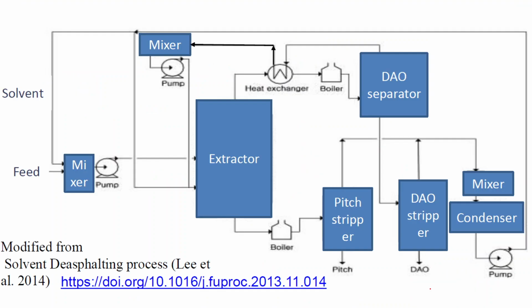So this is the flow sheet for a de-asphalting unit. We take the feed, which is basically our vacuum residue, along with the solvent, either fresh solvent for the first time, and after starting the unit, the solvent taken is the recycled solvent after each cycle. Moreover, regeneration or addition of fresh solvent from time to time is also done.